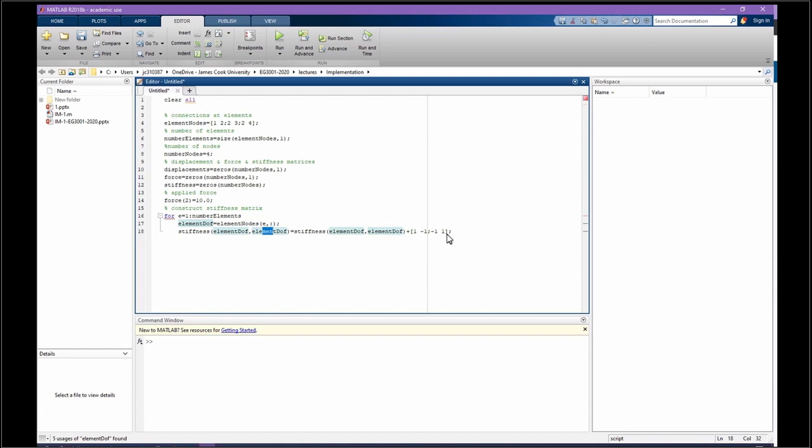So we're not going to make mistake anywhere. And we decided to consider K1, and all of the K's are similar, so I didn't consider any different stiffness matrix. But adding different K's would be very easy. Okay, done with constructing the stiffness matrix. Now we need to apply the boundary conditions.